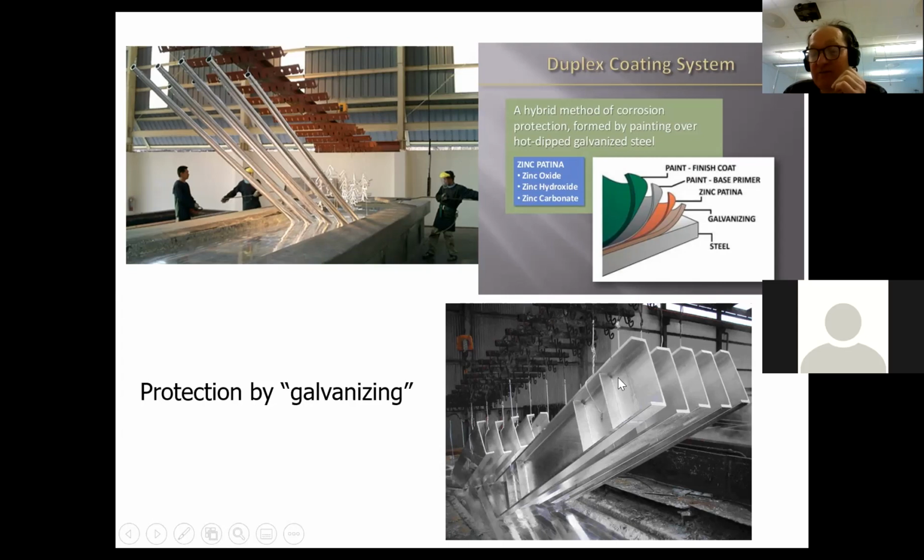And in fact, it'll leave by capillary action, the zinc will suck into all the nooks and crannies and the gaps. So this is an extremely good way of protecting an object which may have many parts to it. And you can see there are several parts here. This is not a single object. You have a U-shaped part here and some bulkheads here, probably welded, I'm guessing. And then the whole lot is put into the molten zinc bath to galvanize it.